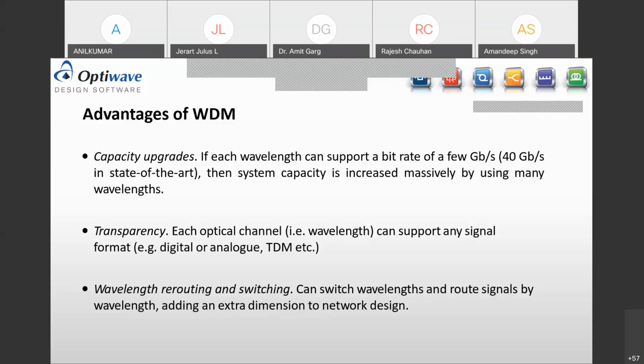In that case, we can compare the results of different techniques, whether NRZ, RZ, BPSK or QAM, so that accordingly we can compare the Q factors, eye diagrams, eye height, amplitude histograms, and bit error rates for specific purposes.